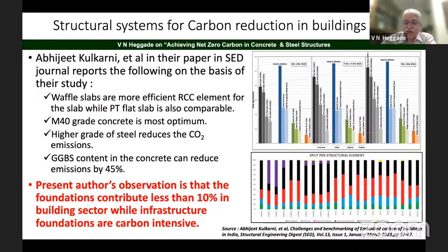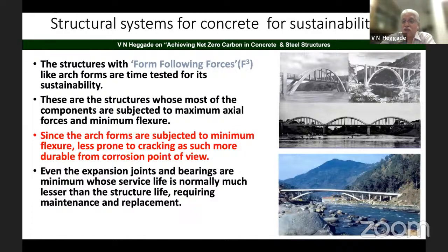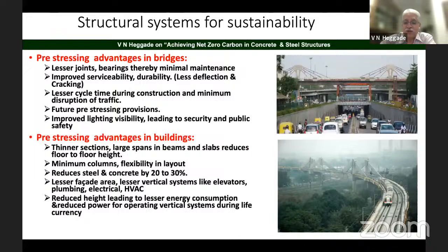As far as the replacement to OPC is concerned, also the arch structural form, as all of you know, is subjected to compression and not much to flexure, because of which it is not much crack prone. I think that is why you see arch structures all over the world lasting for a long time. I think perhaps arch forms can be used as far as possible.